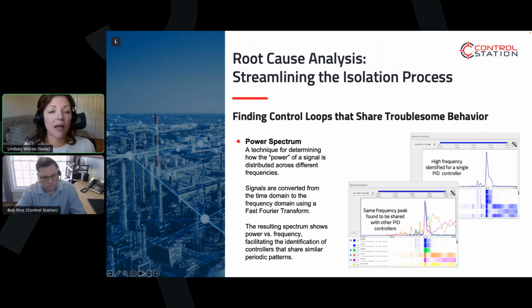One example that comes to mind is leveraging modeling: building a model of our process signals and then evaluating our R-squared values to see what the relationship is between those loops. These are just some examples of different methods that we've used or deployed to identify those relationships between our control loops and process variables.